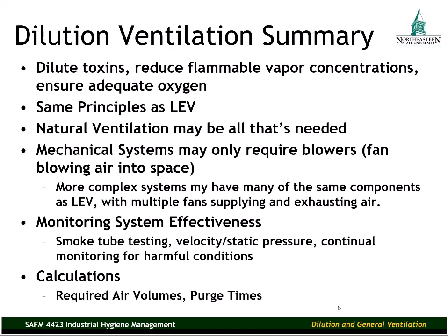A lot of the same principles as with local exhaust ventilation. Pressure, velocity, volumetric flow rate, a lot of the same variables are involved. Now, one thing we talked about, in many cases, natural ventilation may be all that's needed. But in other situations, mechanical systems may need to be implemented. But if we have to implement a mechanical system, it may only require one fan set up as a blower, blowing air into the space. But it can also range all the way up to the more complex end, where some of the more complex dilution ventilation systems may start to look a lot like a local exhaust ventilation system.